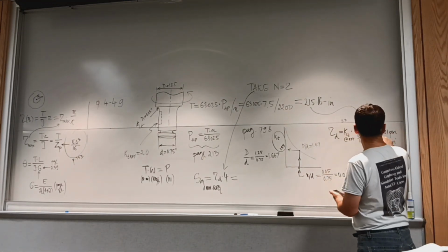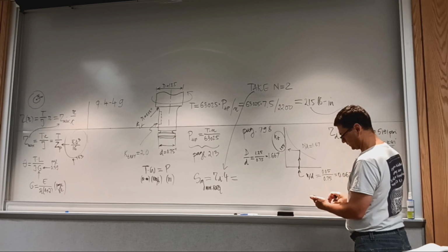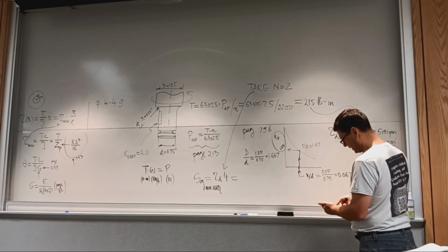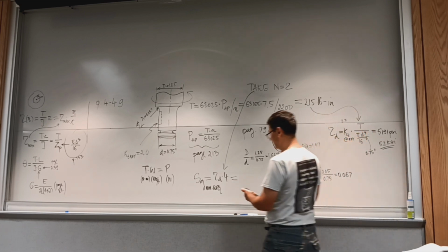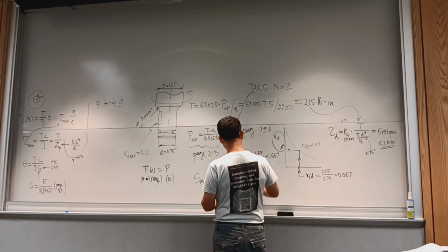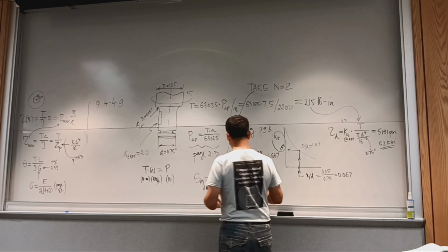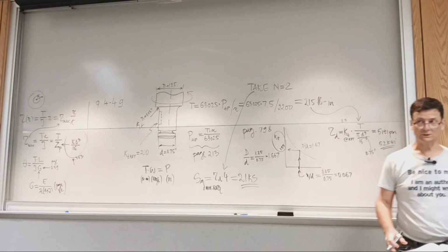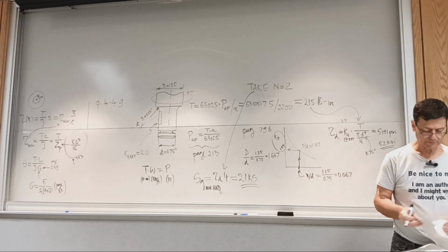So this is a small value over what carbon steels can do. So times 4 now, and then over 10 exponent 3 to get in ksi. So it'll be 20.76, 21 ksi.